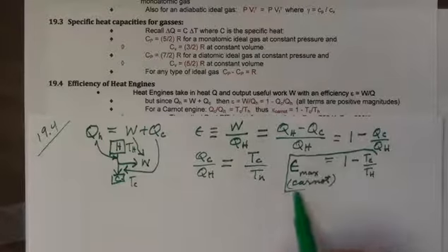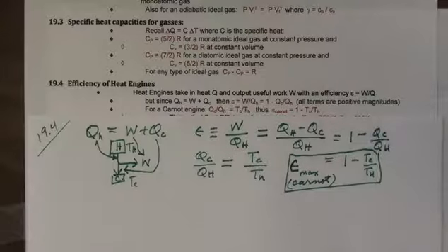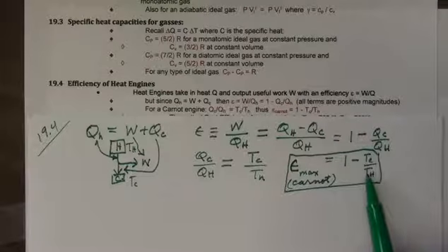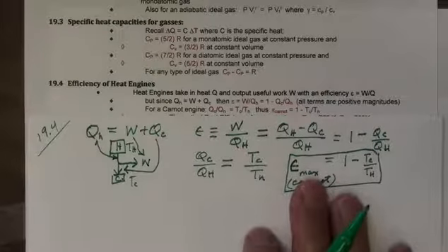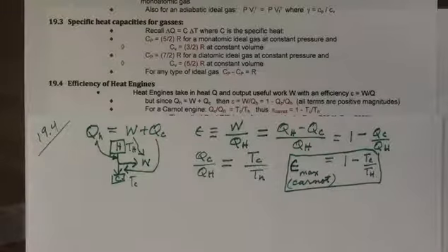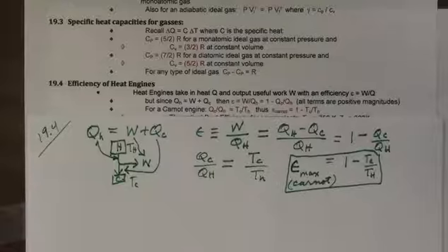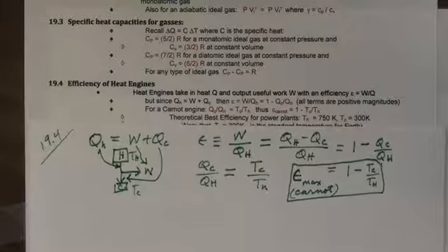This is an incredibly important equation because this says in order to have really high efficiency, we must have, and of course these temperatures are in Kelvin as they always are in thermodynamics, this must be a very high temperature and this must be a very low temperature. So now we know what kind of efficiency could be obtained. Now this does not cover things like friction. You're going to have frictional losses, transmission losses, storage losses and so forth. This is just to get the work out of the system.